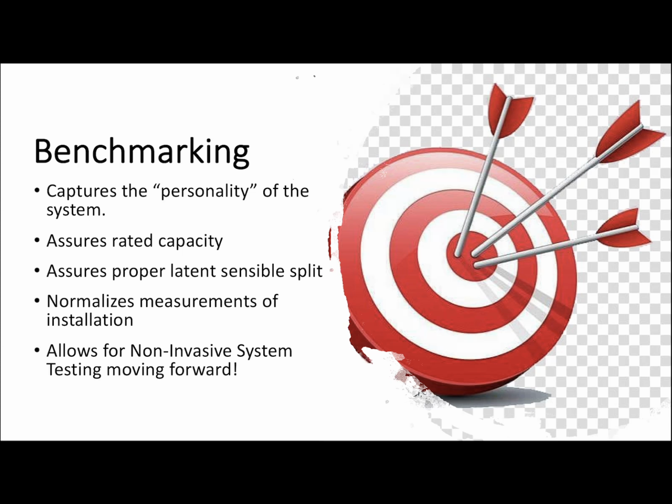Benchmarking now captures the personality of the equipment. Remember before we said we did a profile. Profile is how it would typically operate. Benchmarking captures a personality or its installation variable. So it captures the impact of the ductwork that's attached to it. It captures the impact of the fan speed you picked. It captures the impact of the charge that you have. It captures the impact of the line set length.